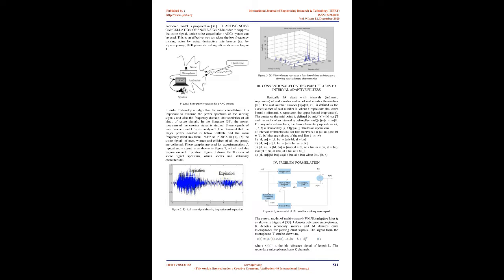In 13, 14, an extended interval Kalman filter is used to estimate the values related to localization and mapping. Interval Kalman filter obtains the bounds on the estimated value. The actual estimates are computed at each time step, which is the weighted average. The system instability can be controlled by this trained method and can be used for tracking missions 15, 16.